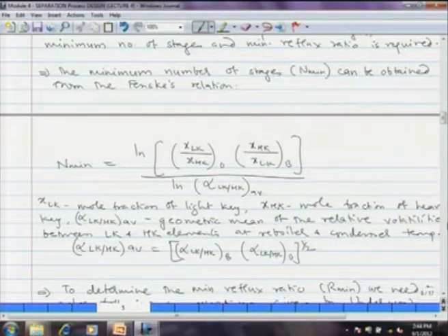Okay. In that case, you had defined Xd and Xb, where you had only two components, one more volatile and the other less volatile, then Xd by Xw, the mole fraction of the more volatile component in the distillate divided by Xw, the composition of the more volatile component in the bottoms. Exactly the same thing is here, but we are now defining Lk and Hk components, which are the light key component and heavy key component.